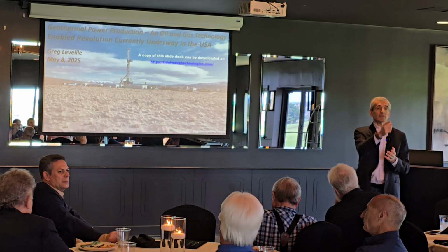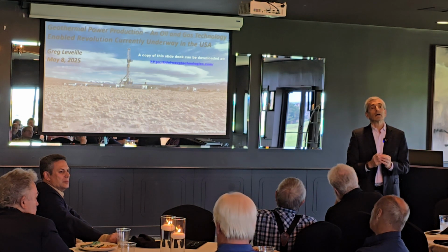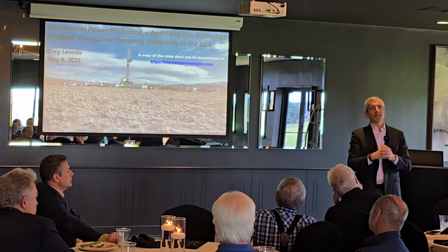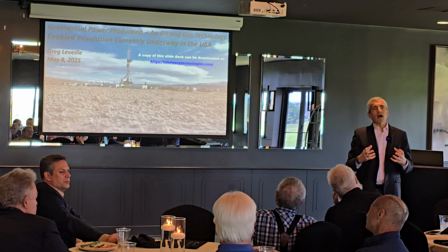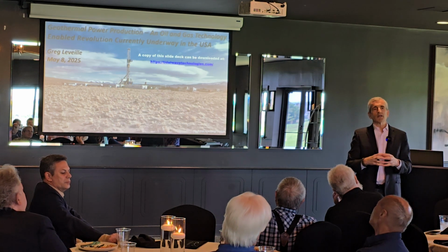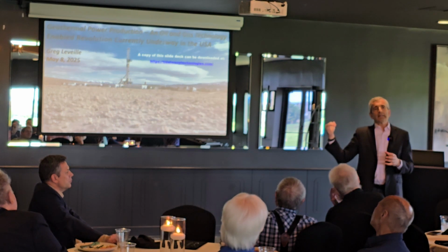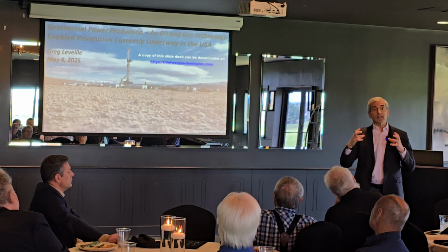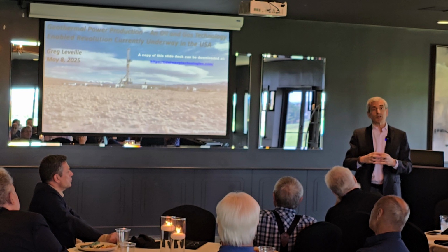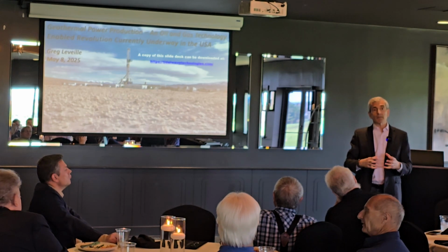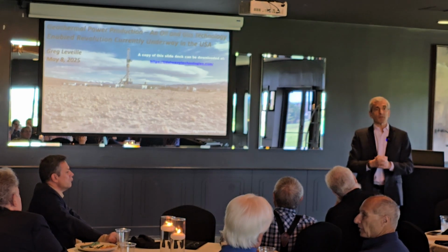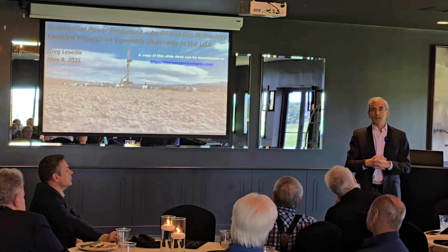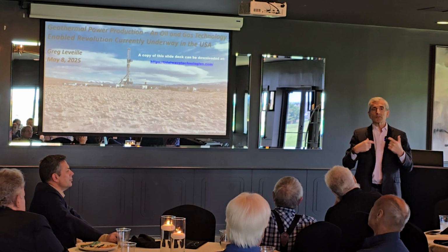Is there any use for old depleted oil and gas wells in this aspect? Yeah. Matt and I were talking about that at lunch. One of the challenges with the old wells for the type of power generation I was talking about is the wellbore casing sizes are generally too small. If you want to be doing 25 to 50,000 barrels of fluid a day, you ain't going to do that with most of the wells we've put in the ground. But there are some other uses.